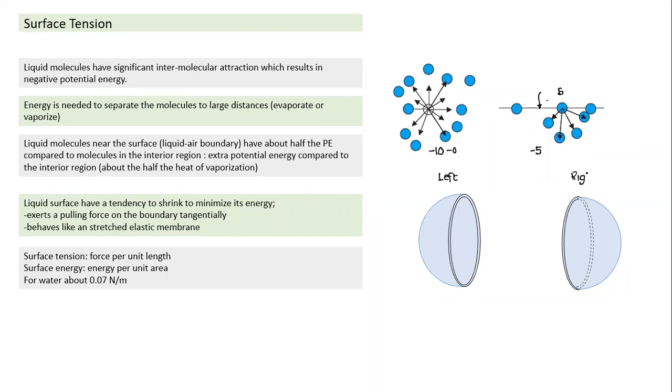If we consider the whole bubble together as a system, surface tension becomes an internal force. It does not come into the equation. So whenever we want to analyze surface tension, we need to take a part of the bubble. Let's take the left part. This left part also tends to shrink, so it exerts a pulling force on the right part. The right part has two boundaries, the inner surface and the outer surface. On these surfaces, the left part exerts a pulling force like this. Similarly, on these two surfaces, the right part exerts a force like this.